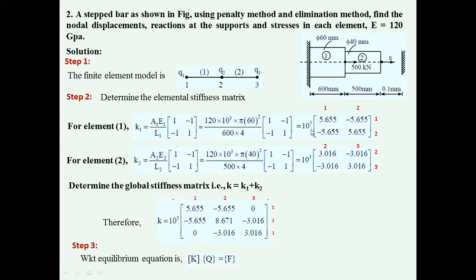You remove 10 to the power of 5 outside and send the term inside. So you'll get 5.655, minus 5.655, minus 5.655, 5.655. Since the element consists of the node numbers 1, 2, you represent here 1, 2, 1, 2. You find out the stiffness matrix for element 2, K2, which is equal to A2 E2 by L2 times [1 -1; -1 1], which is equal to...